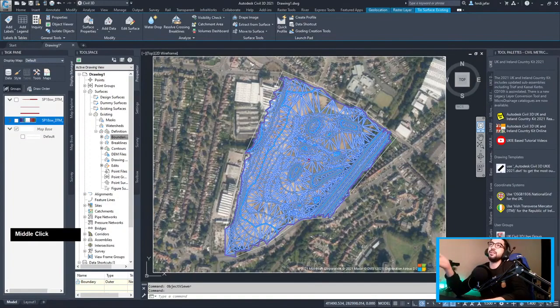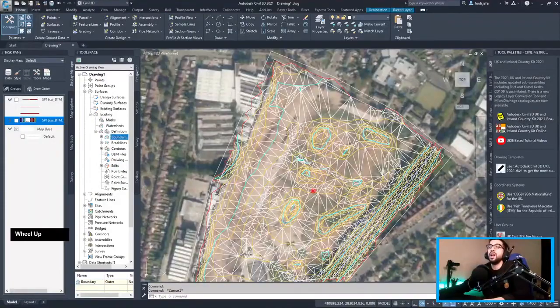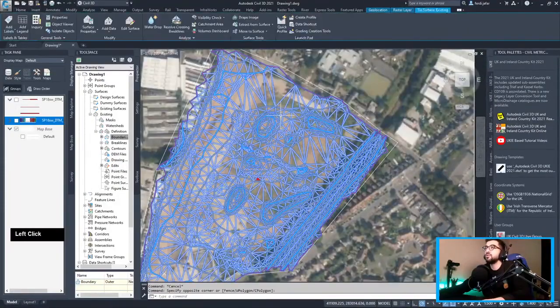But yes, if you don't have access to Civils 3D, you can import the TIFF file into QGIS. However, I think you need to have the GRASS edition of QGIS, which comes pre-installed, I think. And then from there you can export the contours. I'm having a hard time trying to export the contours with a Z value. I can export them without a Z value, but not with a Z value from QGIS. But this way we have a surface model, and yeah, you can start working straight away from it.